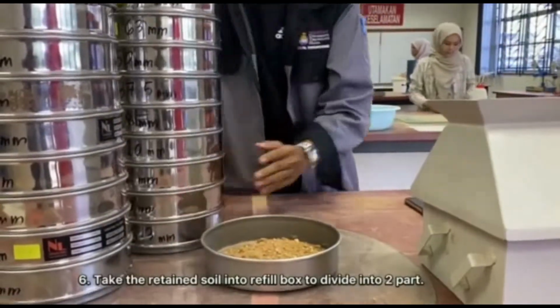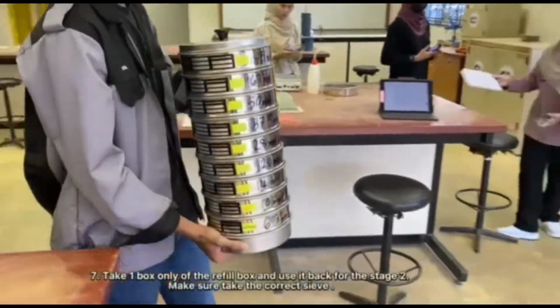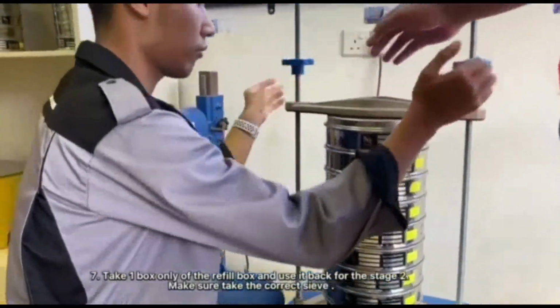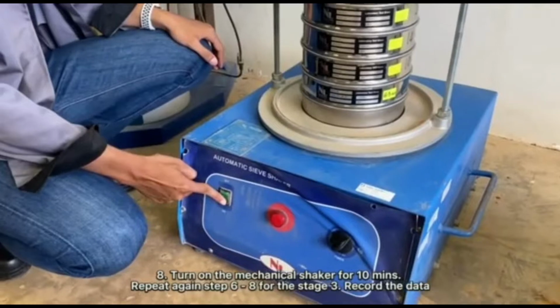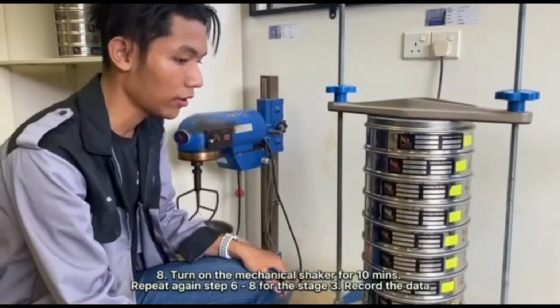Next, take the retained soil into the refill box to divide into 2 parts. Next, take 1 box only of the refill box and use it back for stage 2. Make sure to take the correct sieve. Next, we need to turn on the mechanical shaker for 10 minutes. Repeat steps 6 until 8 for stage 3, and then record the data.